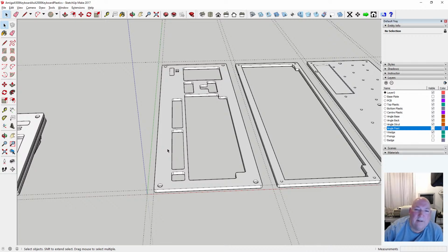I could make one, but then I'd have to run a fly cutter across the surface, I'd have to create a bed, an aluminium bed or something. And if you have a solid piece of aluminium, then you've got no grooves to attach it to, so you'd have to drill and tap into it.